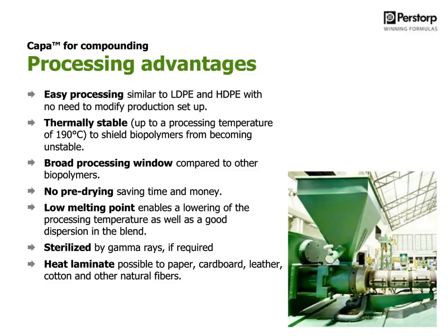Another benefit is also that it's hydrophobic, which means that you do not need to pre-dry it as you do have to with PLA or starches, for example. And here PLA is very sensitive, but by introducing the PCL into your compound, it reduces some of the moisture sensitivity, and it also improves the further downstream processing of your compound. The low melting point that I touched upon earlier, it is also good working with these temperature-sensitive materials, and depending